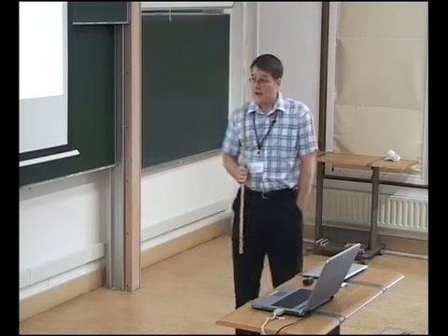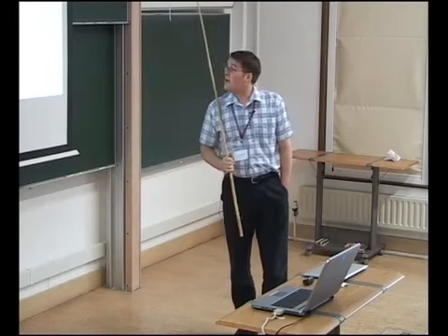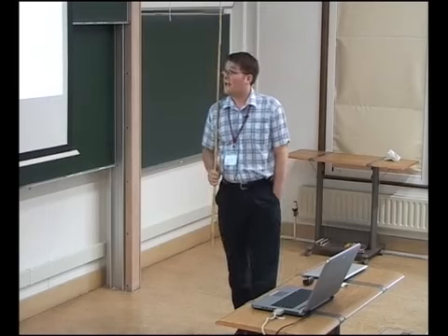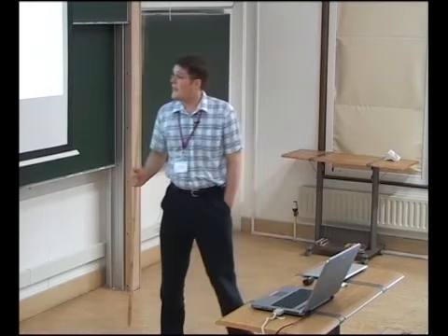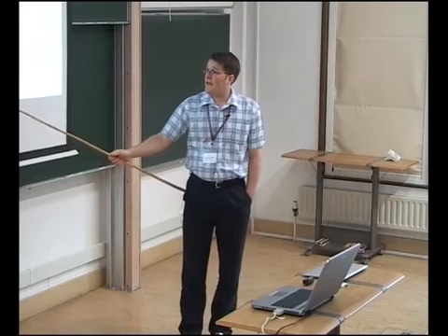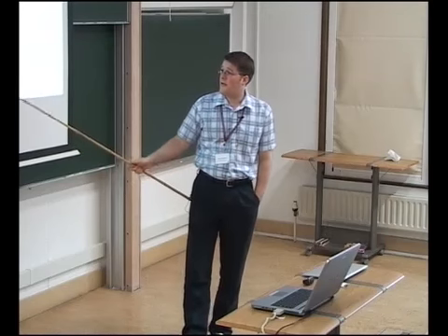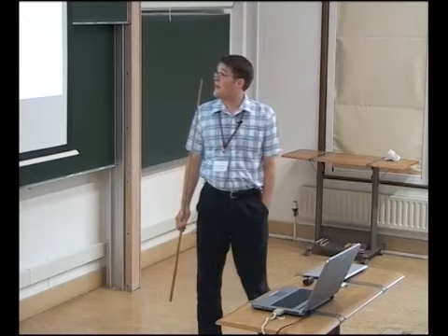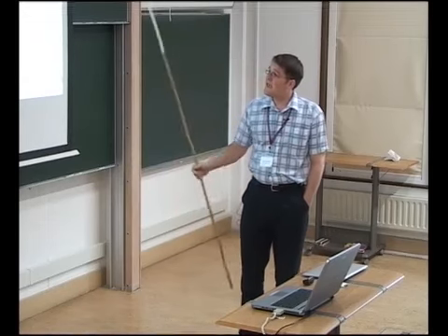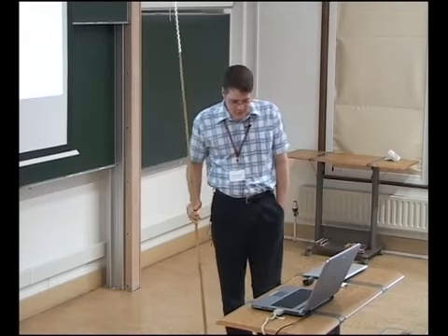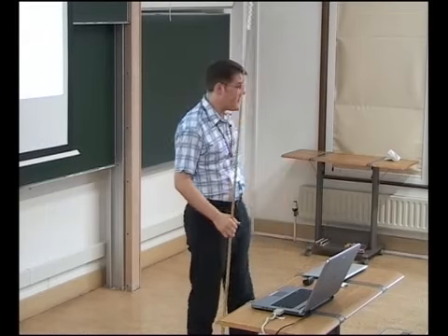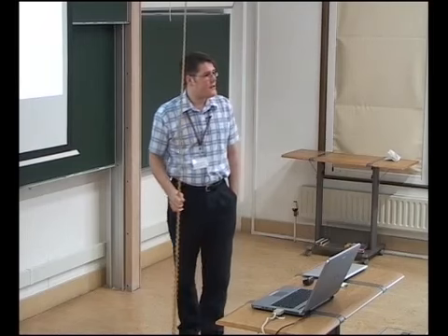Again, simple visualization, comparing fully developed and plug inlet flows, you can get small sinusoidal waves in the shear layer for Reynolds numbers greater than 750 in the fully developed case, greater than 617 in the plug case. And again, 13 years later, just to test PIV in the system, up to 225 with a fully developed inlet,